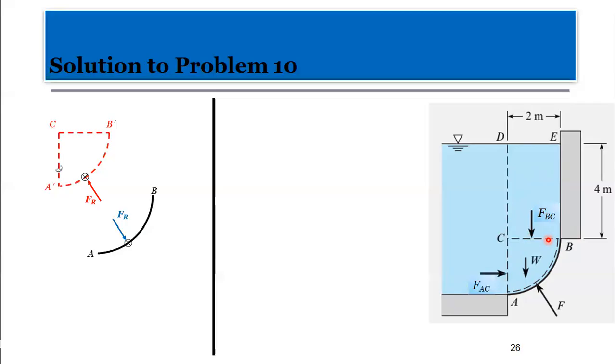All right. So the next step is, first of all, to look at the forces. On gate A prime C, I have what? Force FAC. And it will act at where? The center of pressure. Remember, the center will be somewhere located here. Now, on CB prime, I'll have what? FBC, acting here. It is a horizontal plane, so it's acting on the center.